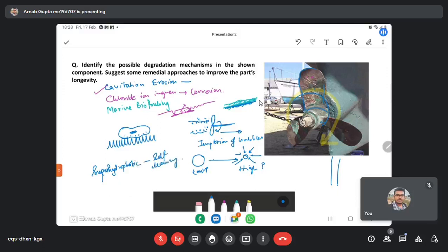So again, we can make the surface in such a way, either chemically or physically changing the topography. We can impose a Cassie Baxter state of wettability on the surface. So what happens is that the contact angle is much higher here in this case, as you can see. The contact angle is much higher.